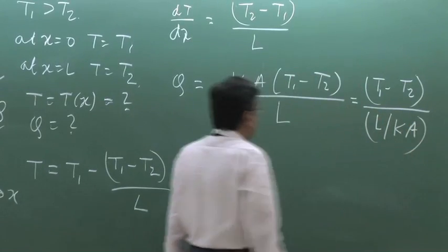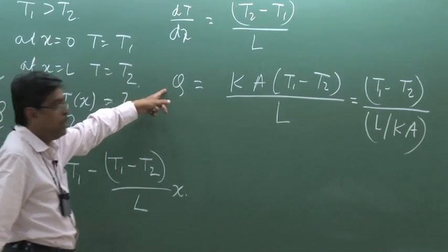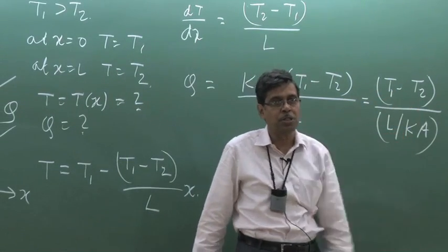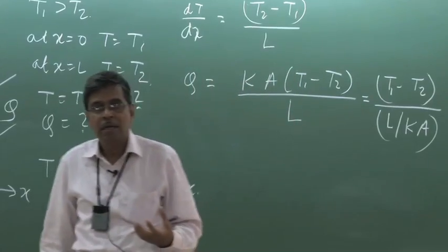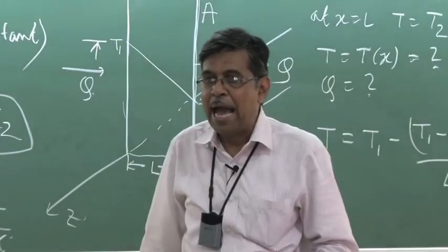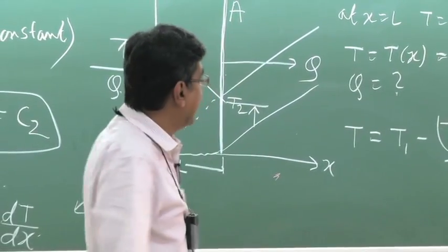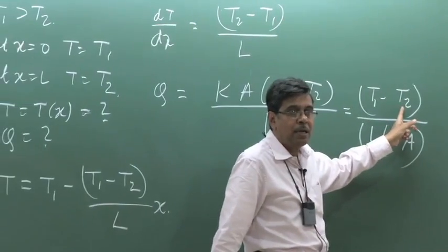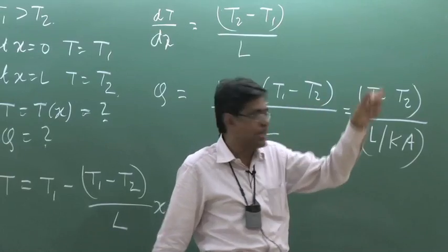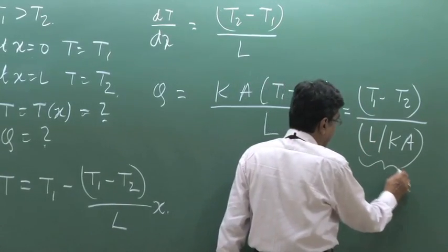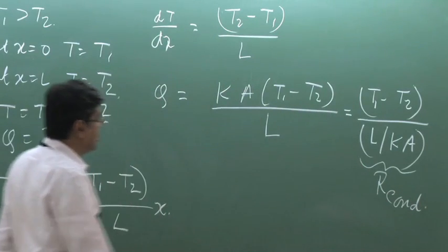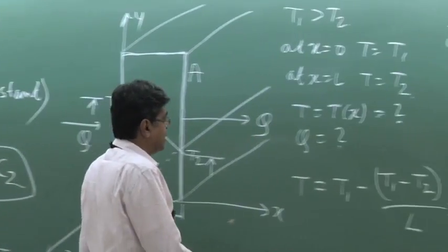Now this looks like an equation that flux is equal to the potential difference divided by some quantity which includes the geometry and the conduction property. That means the length and area and the thermal conductivity. And combinedly this defines the resistance, because flux is equal to the potential difference of that scalar potential which causes the flux divided by the resistance. So this can be perceived as conduction resistance, R conduction, C-O-N-D, I am writing in short,